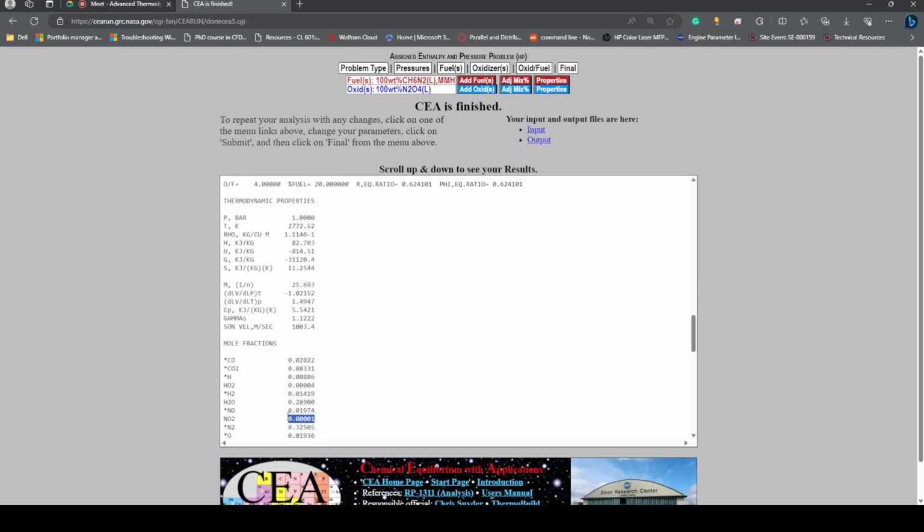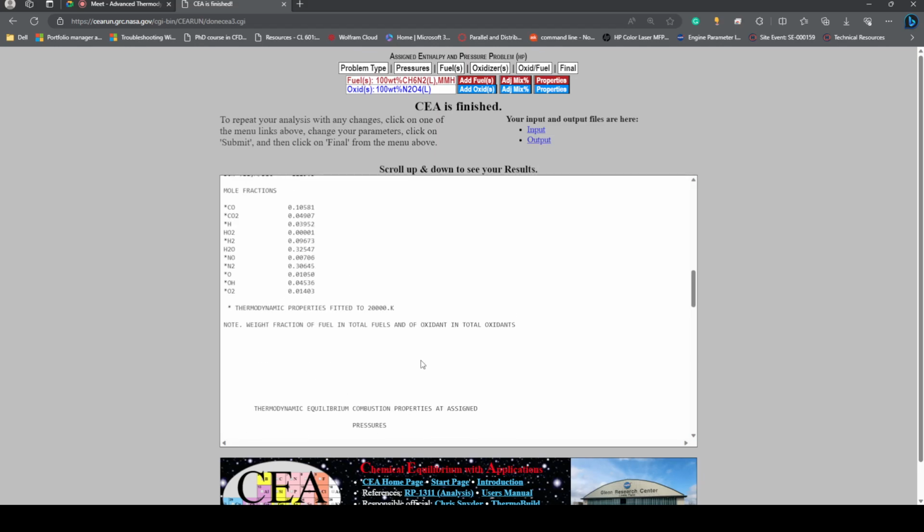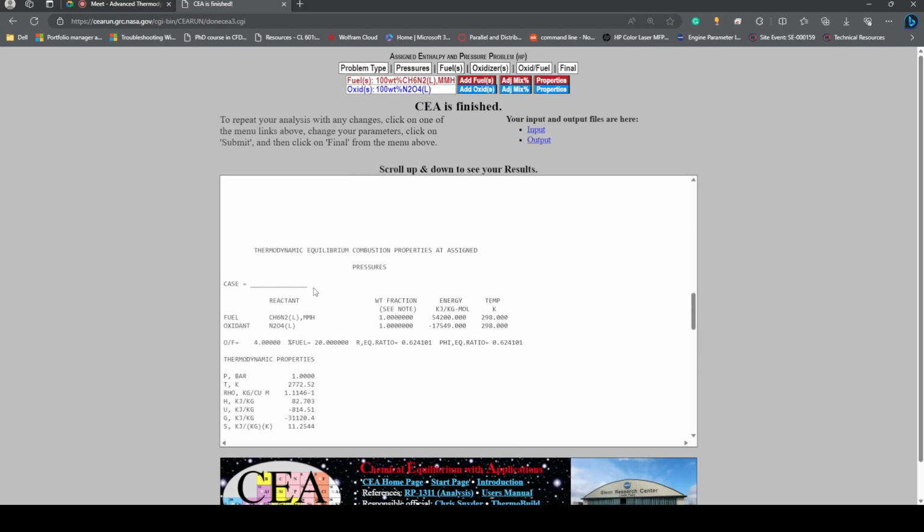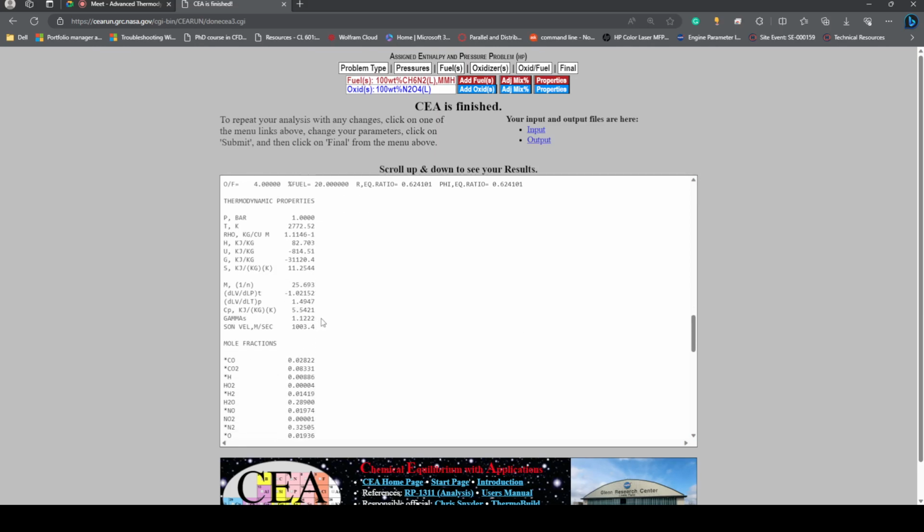If you look at it, this is better compared to the older one. In fact, here there is no NO2, right? But NO is there. So environmentally, a fuel ratio of 2 would be better, but it would be fatal for a turbine. You cannot use it. So people find a sweet spot between these two. Even people use methane also.